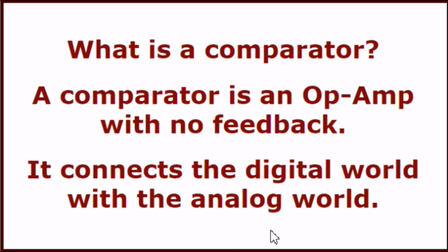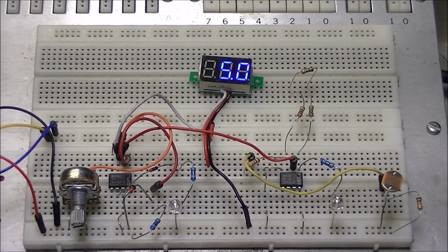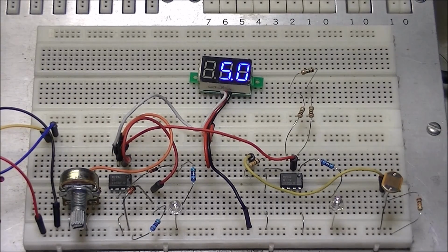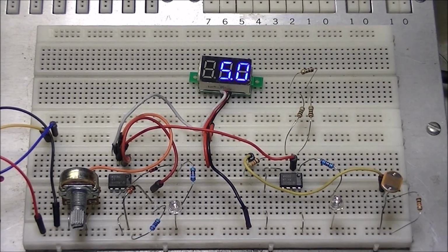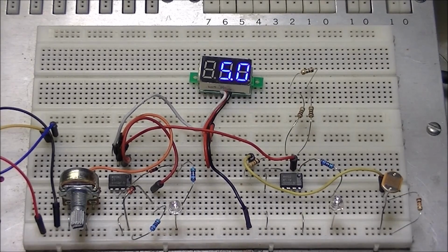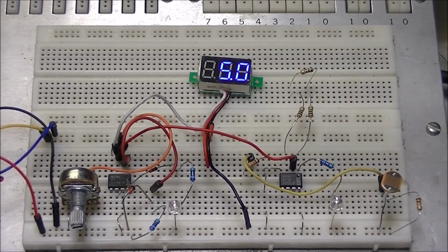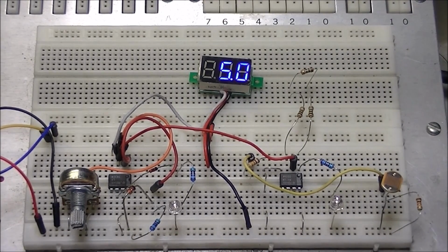First, before we move on, let's watch a short video of two actual comparator circuits in operation. What we're looking at here is two different comparator circuits. On my left here is a 741 op-amp. This is connected as a bipolar, that is, it has a plus and minus power supply. And on the right is an LM358, which is a unipolar device. Both are operating at 12 volts. And what we're going to look at here is how they operate.